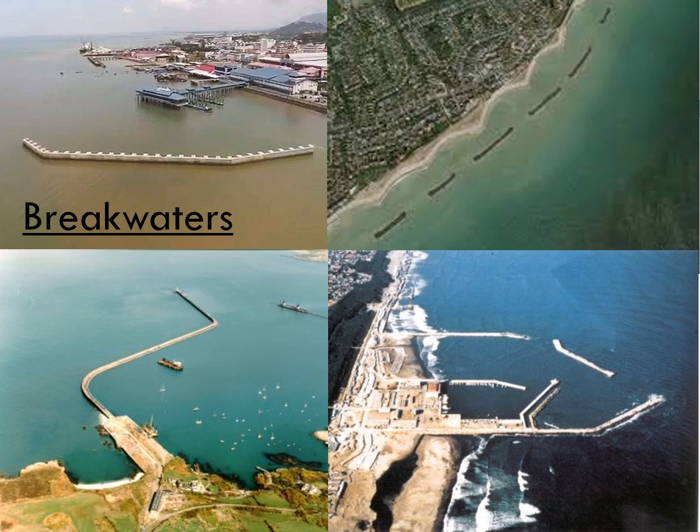For example, we can see in the first figure here a detached breakwater which is meant to protect a jetty in this location. Notice that there's no protection on this side, which might mean that the predominant wave energy usually comes from this direction.